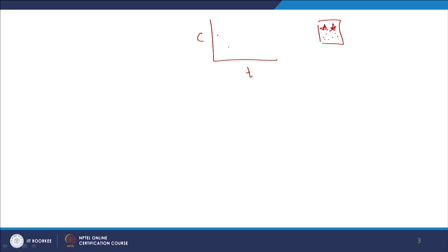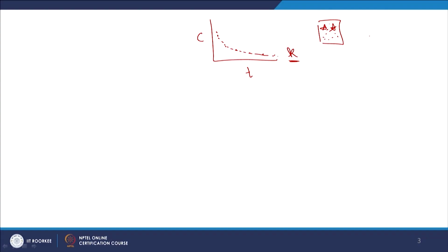So I am going to have samples at different times, and I will measure the concentrations at those times, right. And then I can fit a model by regression and get the relevant k value, right. So I can use this k value then for my particular PRB case, right. So this is applying the mass balance for the batch reactor, and then I will get the K value, and then I will apply that in my plug flow reactor, right.